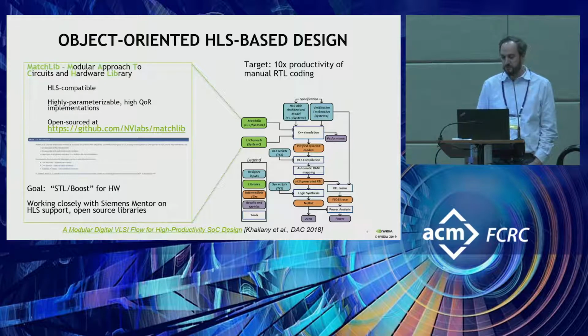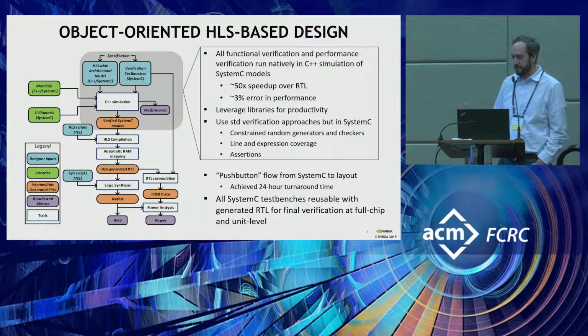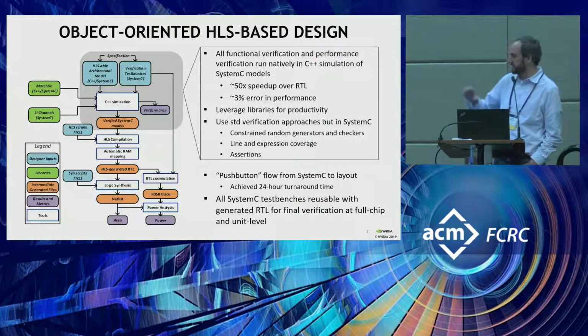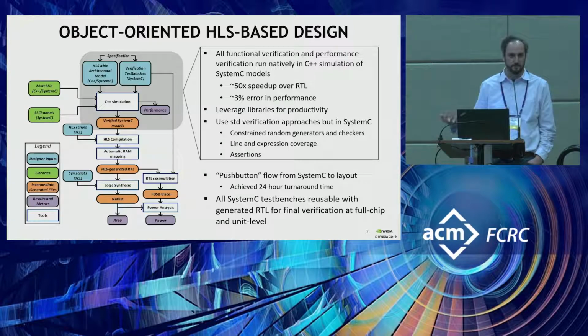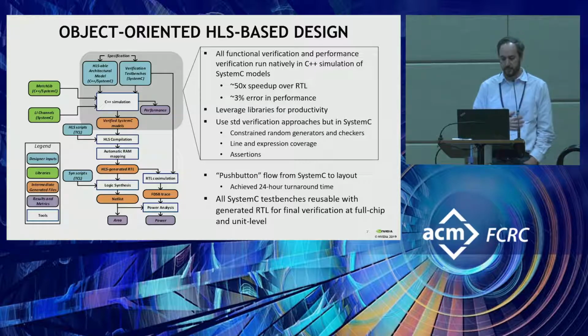We have some empirical evidence from our projects that doing this gets us about a 10x productivity gain compared to manual RTL coding, which is great. But the key thing is, once you have coded your design fully in C++ and linked it with this MatchLib library, shown in the upper part of the box, we want to code our architectural models in C++ and then simulate them in SystemC for logic verification and performance verification. Everything from there down, the intention is for it to be pretty much push button.